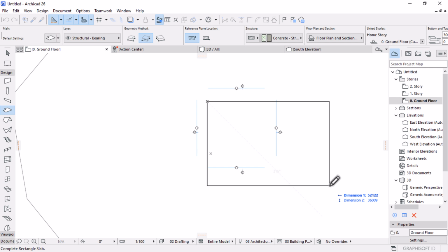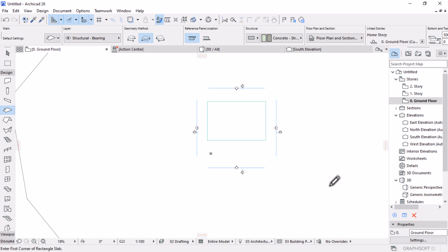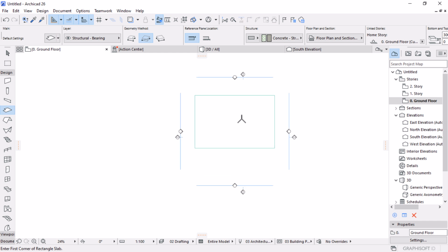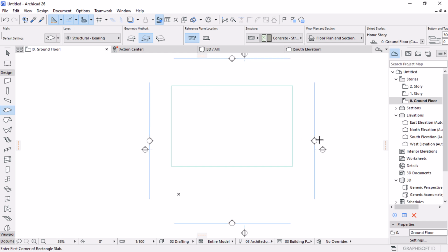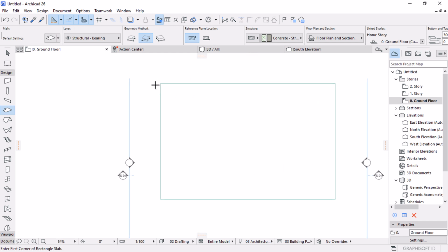It's going to be 25 meters, and then I'll click the downward arrow on your keyboard to key in the vertical dimension, which is going to be 16.6, which is 16,600 millimeters. I'm using millimeters for this, and then hit enter. That's basically the footprint of our building. The slab, including the walkways or the apron, right?